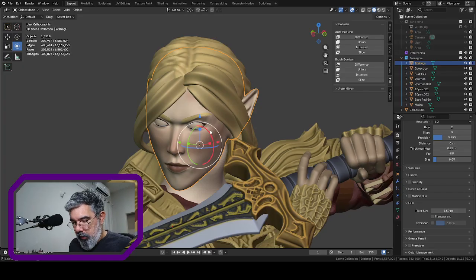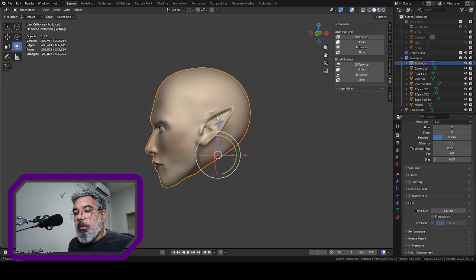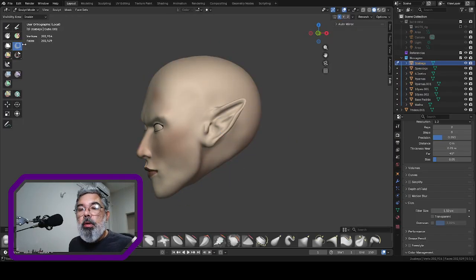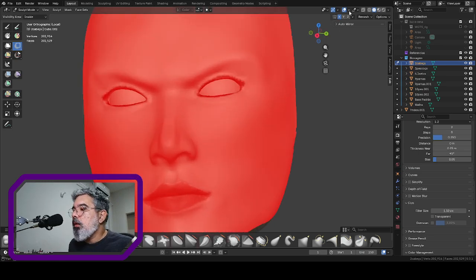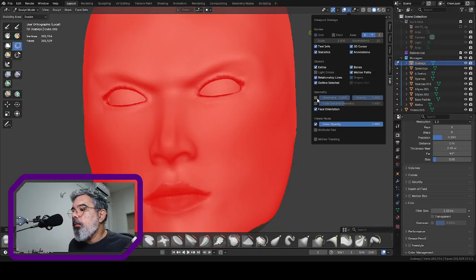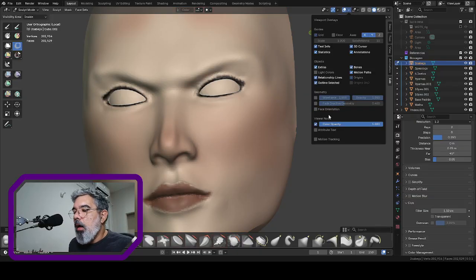Okay, I selected it. Let's isolate it in sculpt mode. Now if you use this hide box, you can see that inside part. Let me turn off the face orientation. I use it because sometimes when you use the Boolean, if the face orientation, the normals, are upside down, that's going to make a problem for your STL file for print.